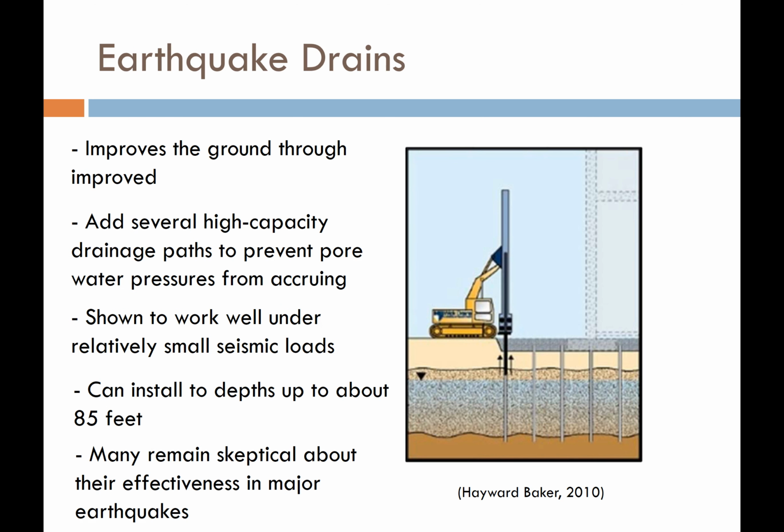Another technique that is gaining more and more traction is the use of what we call earthquake drains. Everyone in this class should be familiar with the idea of prefabricated vertical drains, or PVDs, also known as wick drains. Earthquake drains have a similar concept, but if a wick drain looks something like this and has some ribbing on it, an earthquake drain is basically like this, and it's completely open. It's just like a giant PVC pipe that's perforated, basically.